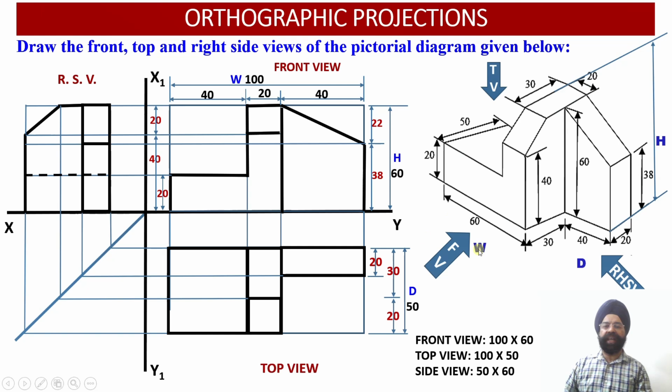Now please check another thing I have done. Because the total height was given to me, I had divided this for the purpose of simplicity, or getting more insight into the construction of the orthographic projection. Because if I show the total height and these two, this adds redundancy over here also. 50 is there, and 30 and 20 I had mentioned. Over here again it was 60, 40 and 20. So the extra dimensions I have now removed, so that the complete construction could be obtained regarding the orthographic projection.